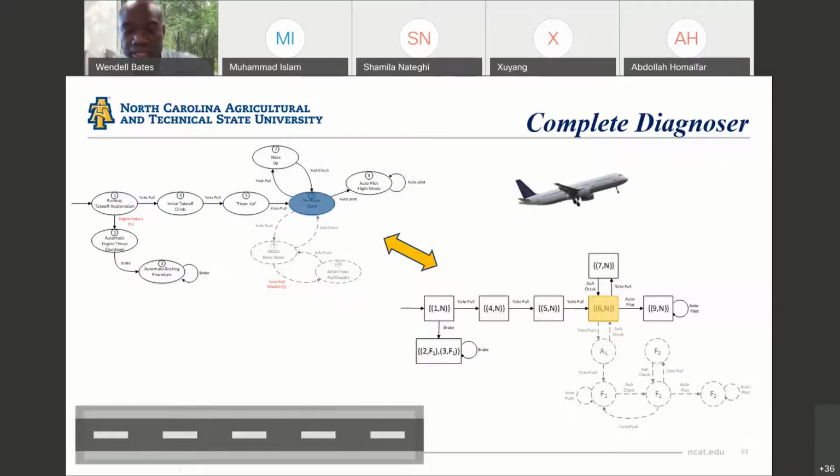and then we start our en route climb. However, in the case that the MCAS was working in the background, the plane would immediately start to pitch down. And so the pilot's initial reaction would be to pull back on the control stick in order to make the plane pitch up. The plane would not respond and would continue pitching down.